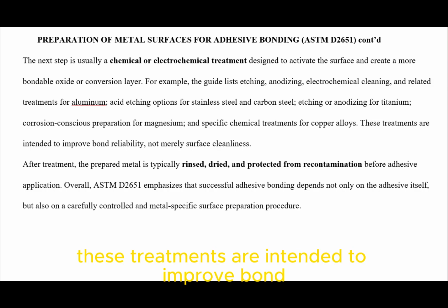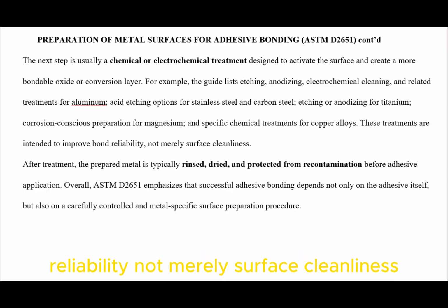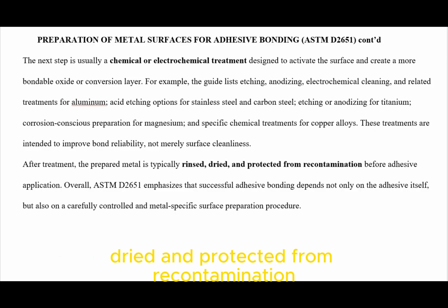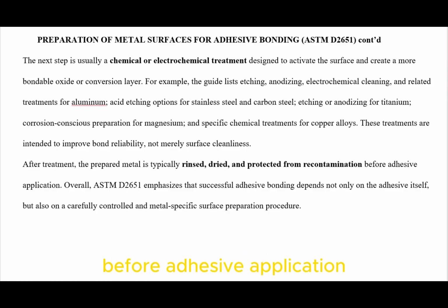These treatments are intended to improve bond reliability, not merely surface cleanliness. After treatment, the prepared metal is typically rinsed, dried, and protected from recontamination before adhesive application. Overall, ASTM D2651 emphasizes that successful adhesive bonding depends not only on the adhesive itself, but also on a carefully controlled and metal-specific surface preparation procedure.